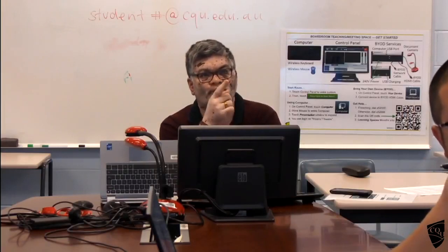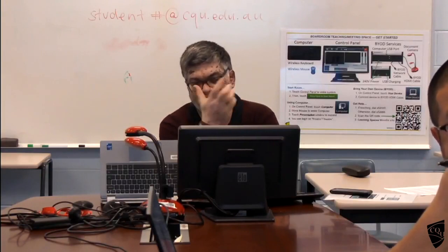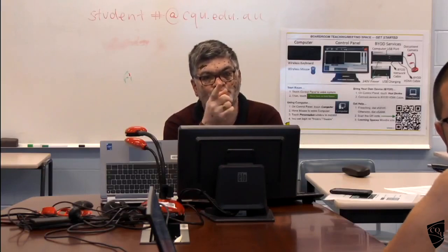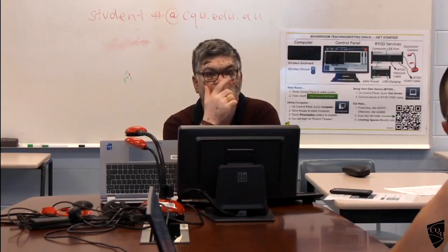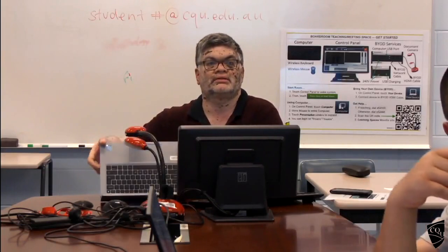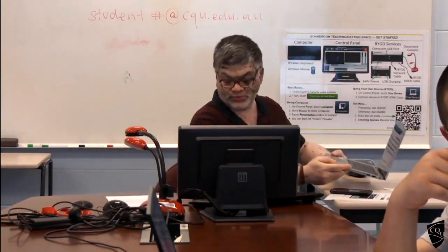For two-way slab, we will get everything from here. For two-way slab, rectangular slab supported on 4 sides, K3 should be 1 and K4 should be taken from this table. Depending on the edge condition, you should be able to get the K4 value from the table 9.4.2.